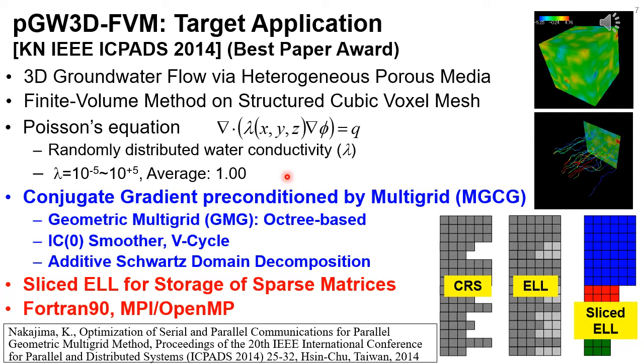Each mesh is a cube, and distribution of the meshes is structured as finite difference type voxels. The conjugate gradient solver with multigrid preconditioner, MGCG, was applied for solving derived linear equations. A very simple geometric multigrid with a V-cycle algorithm is applied, where 8 children form one parent mesh in an isotropic manner for structured finite difference type voxels.